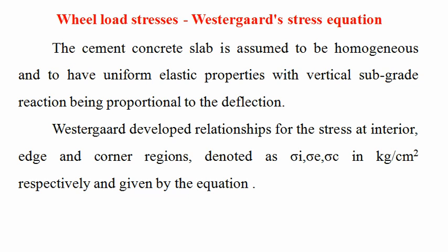So the first case, the wheel load stresses as per the Westergaard stress equation. The cement concrete slab is assumed to be homogeneous and to have uniform elastic properties, with the vertical subgrade reaction being proportional to the deflection.